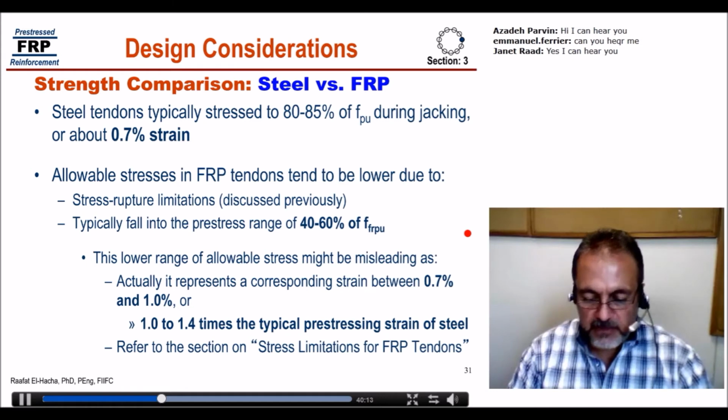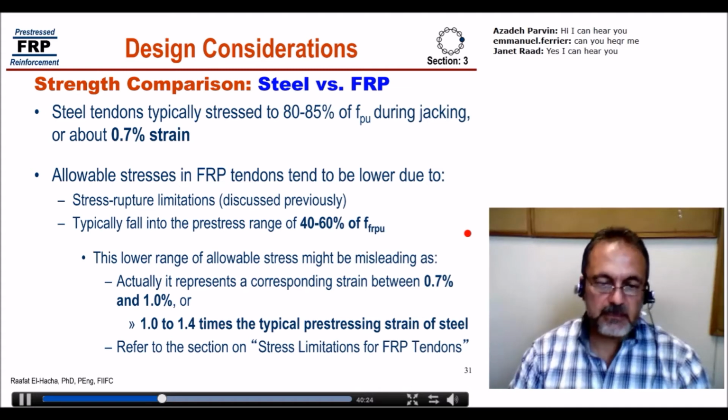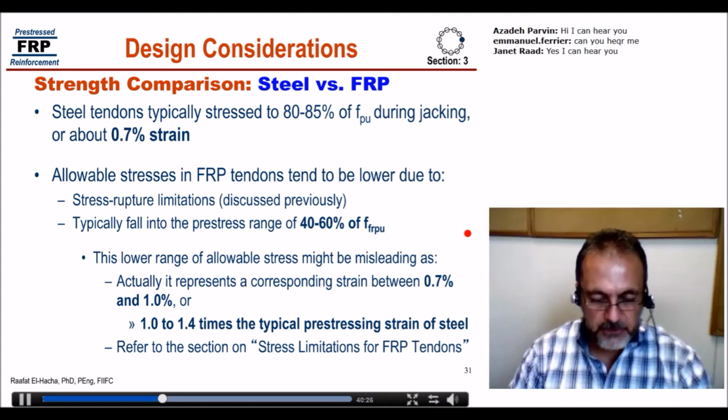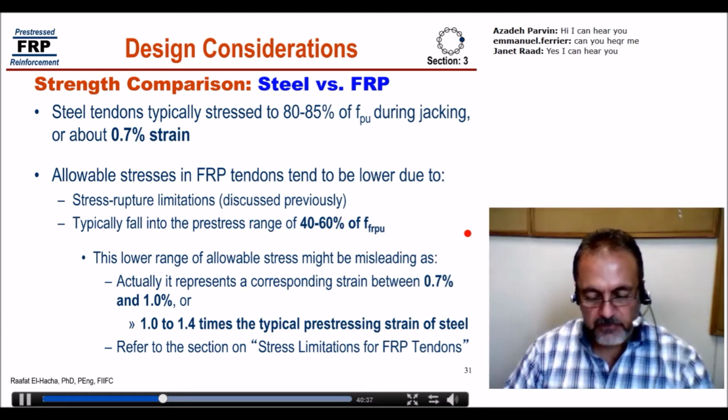So now many researchers have assumed that since large deflection can be achieved in members pre-stressed with FRP tendon, the ductility requirement, we can talk about this later on, can be satisfied. So this is a very dangerous assumption, since large deflection may be due to the low modulus of elasticity of the reinforcement, okay, and may correspond to large amount